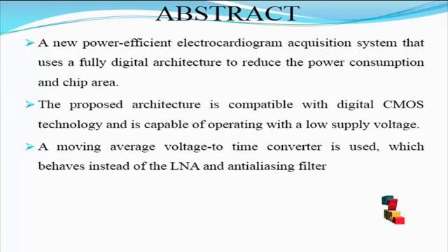Biomedical signal acquisition systems typically consist of a low noise amplifier, a band pass filter, an analog sample and hold, and an analog to digital converter. With the advancement of CMOS technology, the supply voltage is being reduced, which decreases the voltage headroom for analog blocks of an IC.